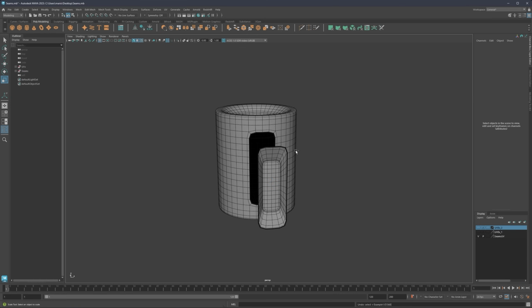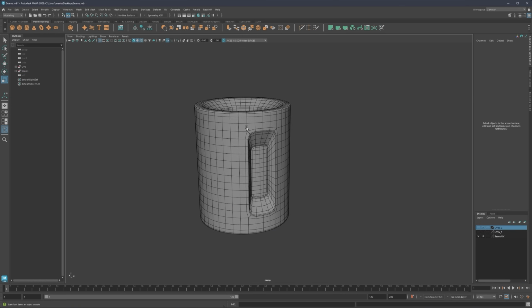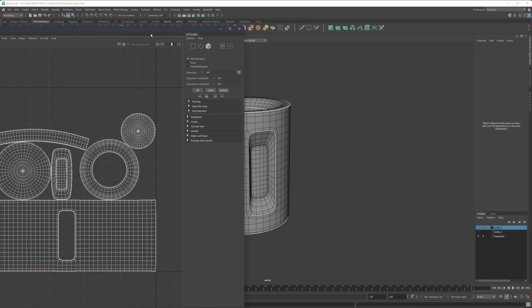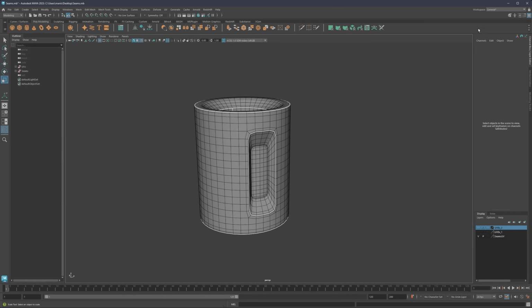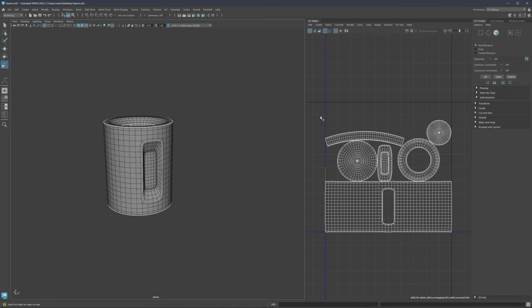I'm going to show you one more thing. All right, so I'm going to show you now how these seams would look and how UVs would look. I'm going to go here to Workspace, General, and we can go here to UV Editing, or alternatively here UVs and then open UV editor. If you click it here, then you're going to get this floating window like so. And if you go to workspace, UV editing, then you're going to have more of an optimized workspace where basically this UV window from here is just docked on the side.